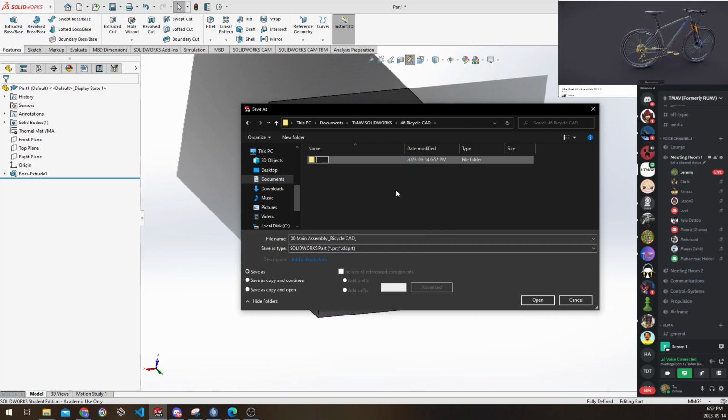For example, we would have 01 dash propulsion, let's say. 02 would be wing structure, 03 would be structural, 04 would be avionics, something like that, just to break up the sub CADs, and then in this main folder we'd still have our main assembly. Okay, we don't have to worry about that for this case, just to show.